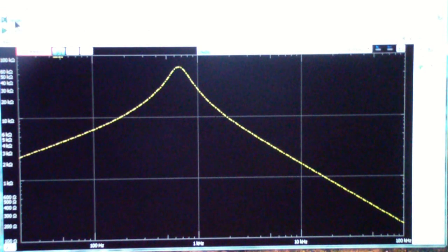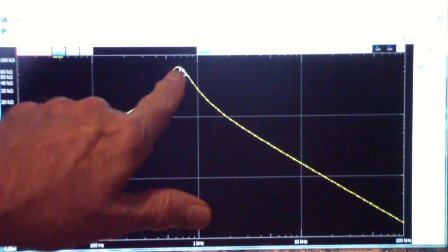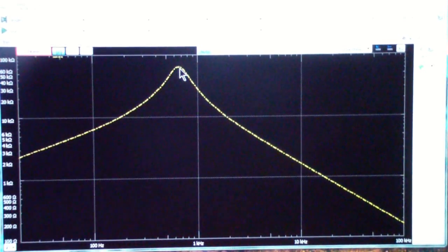So what we've done is, by removing the speaker impedance, we have increased the impedance at the output, and therefore the reflected impedance is different. Now notice that it goes from 2.5K, where it originally was, which is basically a characteristic of the transformer, to a high of certainly more than 60, it looks like about 75 kilohms, at this same point, which is probably at or near the resonant point of the transformer itself.